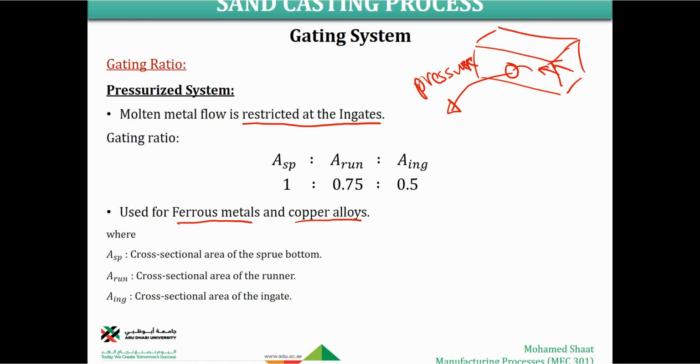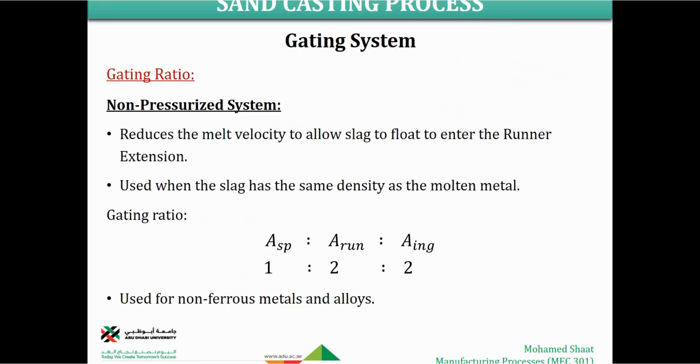This is the same thing here. You're putting a small opening and there is lots of pushing of molten metal here. So this metal will be grabbed and attracted to flow through this opening. This will attract some other slag material to fill into the mold cavity in some cases.